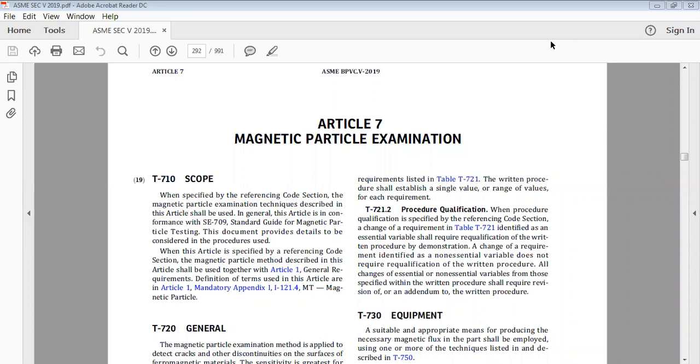So in magnetic particle testing, basically there are two types. One is visible, and the second is fluorescent magnetic particle testing. If you want more sensitivity, we do fluorescent magnetic particle testing. And also if you want high speed of inspection, then also our first choice is fluorescent magnetic particle testing. Okay, so based on sensitivity and speed, for automobile components we are using fluorescent magnetic particle testing. And for example, for welds and other joints, we sometimes do visible magnetic particle testing.